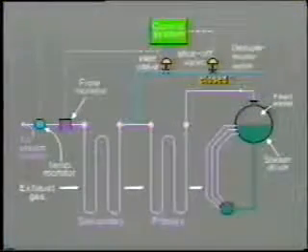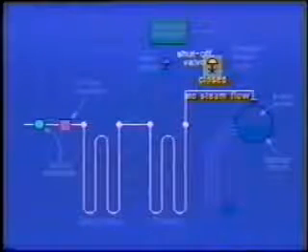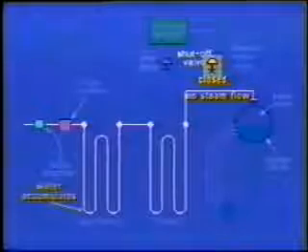This valve is also tripped closed when either the HRSG, gas turbine, or steam turbine are tripped. The reason is there would be no steam flow to prevent the possibility of water entering into the superheater and accumulating. Later, when the unit is started up, this water may be carried into the steam turbine.